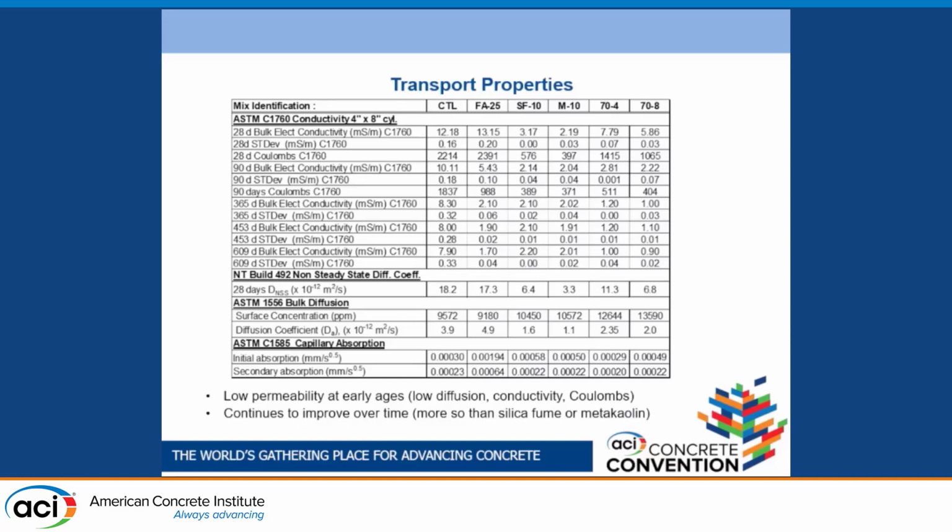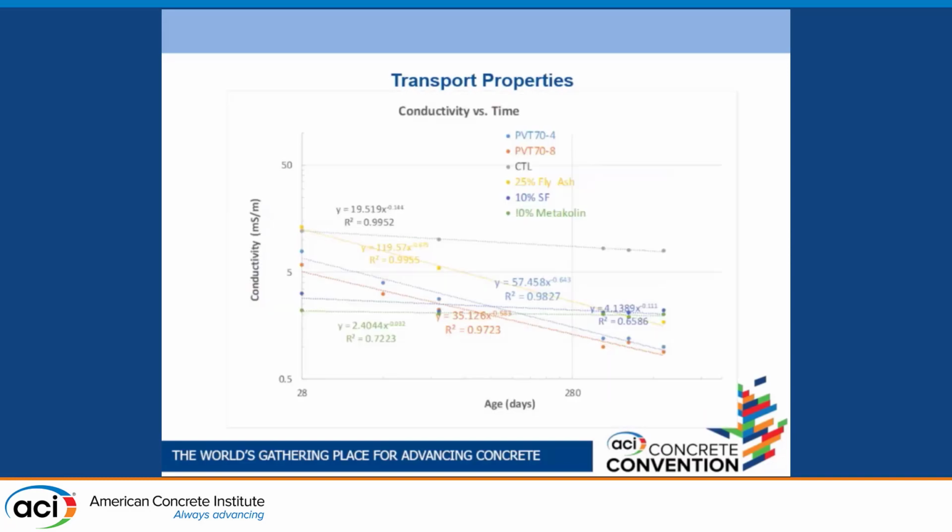Initial diffusion coefficients we can look at, they also start a little bit higher, and then the fly ash got better, and eventually came down also. And the bulk diffusion, you can see 2 to 3.9, and fly ash is higher as expected. And these were lower here, but they came down in time. Water permeability, capillary pore permeability, absorption is also reduced with these materials. So basically, from the point of view of transport properties which are needed for corrosion modeling, they're giving a large benefit.